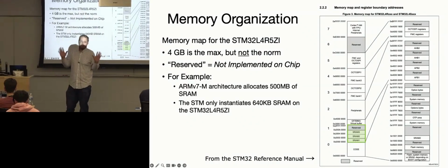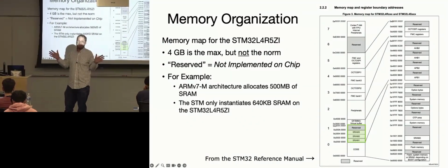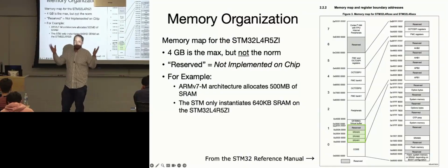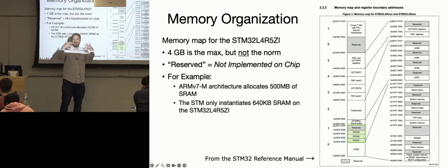From a core's point of view, it's all just loads and stores. It makes things easy for ARM, right? Their core processor just does loads and stores. And then the documentation, or the IDE, interprets that as, okay, this GPIO pin is going to go high or low. You have to know that writing to this memory address means something other than just storing data.